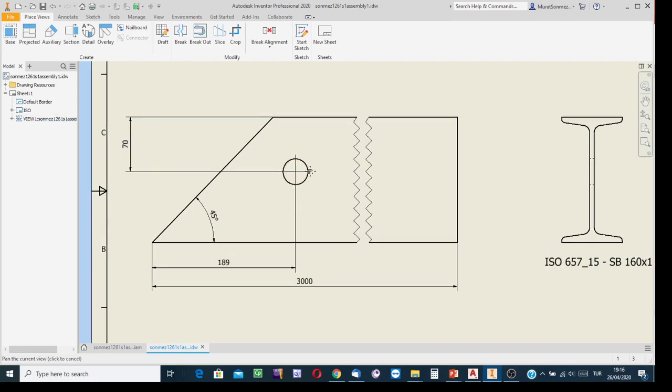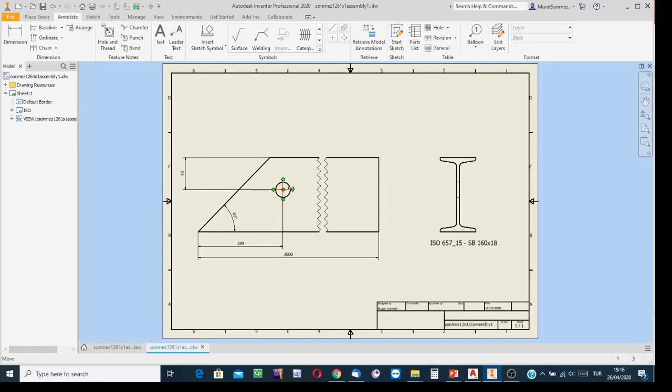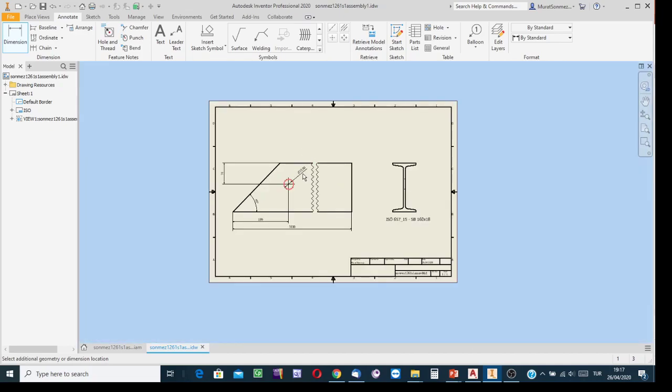And also, yes, I forgot to show the dimension of this hole, say that indicated with a leader line. Then you can show the diameter. It is of course possible, or with a leader line write the standard specification note for the bolt. Say that the hole is for such a bolt or such a cap screw. It is also necessary.